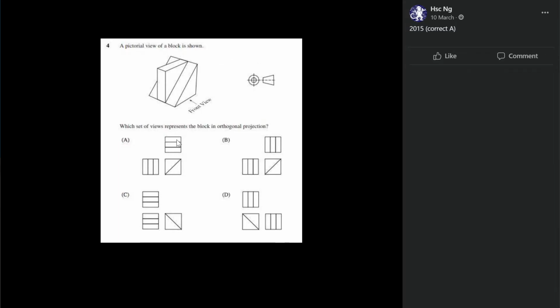So what we want is this one here, A, because it's got this French flag, and the French flag is, if we're looking from this direction, if this is front, then that means we're going to have 1 line, 2 lines, 3 lines, 4 lines, which you can see here if we go from the front. From the side, when we turn this around and look, if we were looking from this side, what will we see? We'll see 3 lines like a German flag, and this one's a French flag. If we look over on this side, we'll just see a rectangle because there's nothing there.